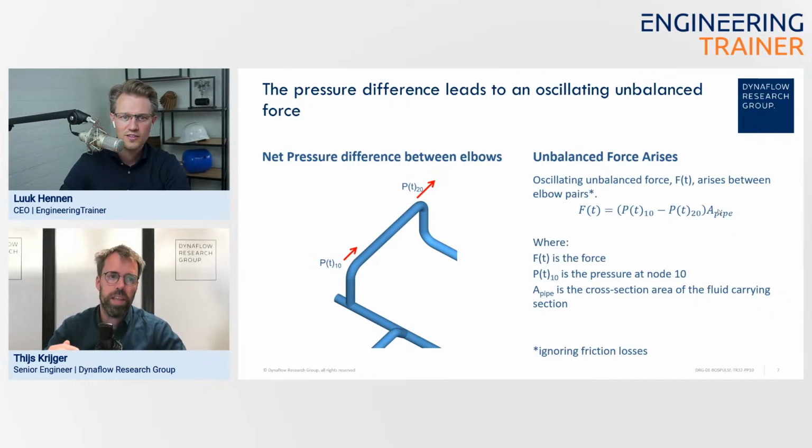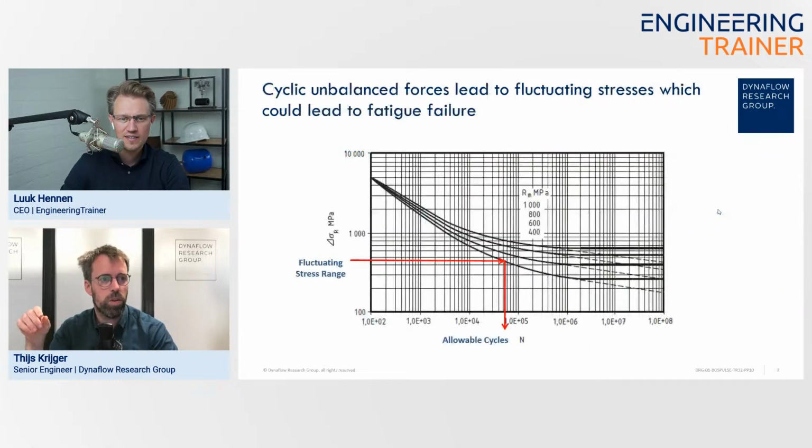Now, besides that running frequency, if you have multiple cylinders that are firing, let's say, at different times along the rotation of the axis, you could have multiples of that. And also, if you have this double acting thing, you also have 2 pulses for each rotation. So then you have a doubling of that frequency as well. So that's the order that we're talking about, and I think it's the next slide as well.